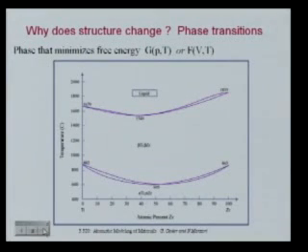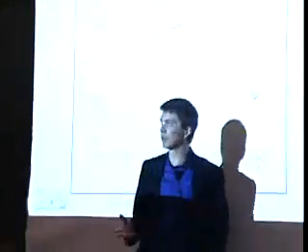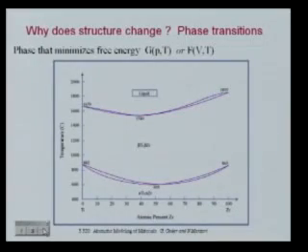Let's say you wanted to be able to predict such transition temperatures. Then you obviously need to get the subtle energy difference between HCP titanium and BCC titanium as a function of temperature. So you need to know what contributes to the entropy of these phases. And you could say, well, I'm really good at my ab initio stuff, so I'm going to do ab initio molecular dynamics. And again, I'm running a little bit ahead. Molecular dynamics is essentially, you let the atoms move according to Newton's equation of motion. So it's essentially doing the vibrations of the atoms.